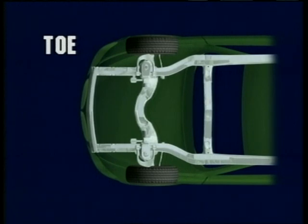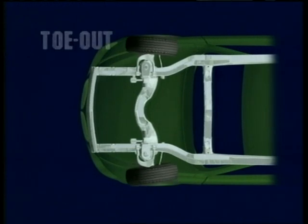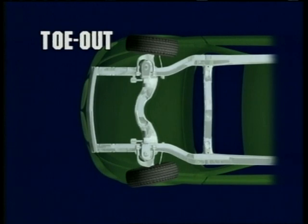Toe is the difference in the distance between the front and the rear of the left-hand and right-hand wheels. Toe-in is caused when the front of the wheels is set closer in than the rear. With toe-in, the wheels are pigeon-toed or point in at the front. Toe-out is the opposite. The front wheels point out or are farther apart on the front than in the rear.